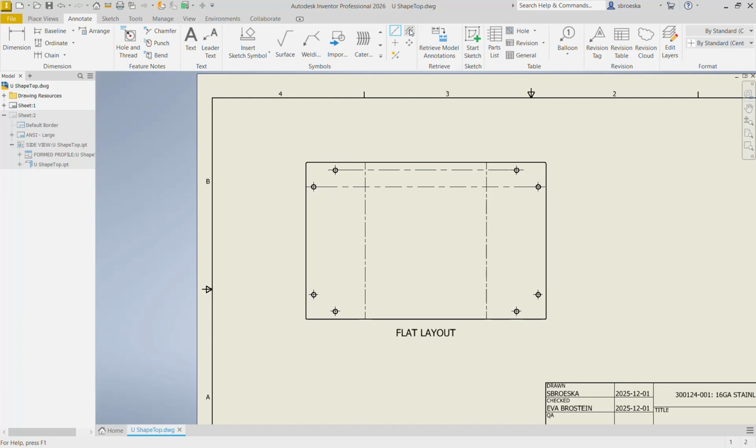If you want lines of symmetry, you can select this icon up here, select one line and another line, and it's made a line of symmetry. I know that I have this feature selected because this icon has a blue outline. If I press escape, that outline disappears, and now my cursor is just a regular cursor again.